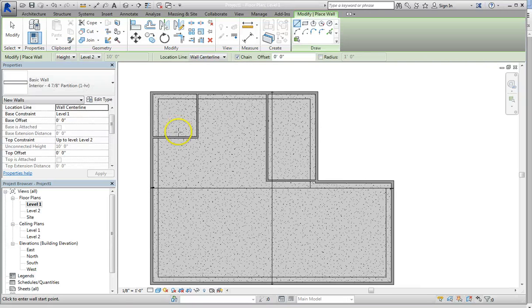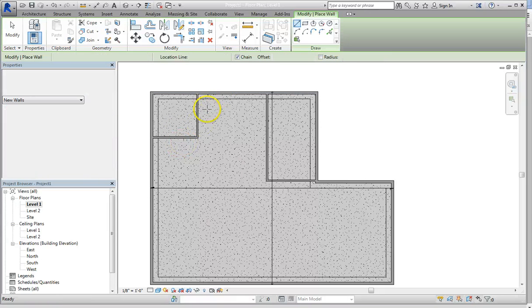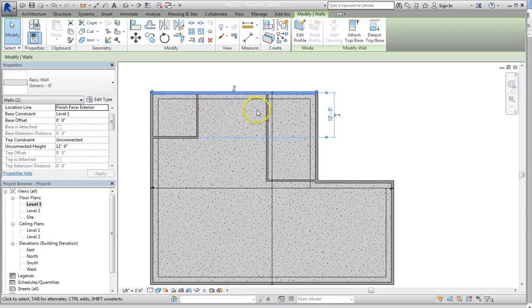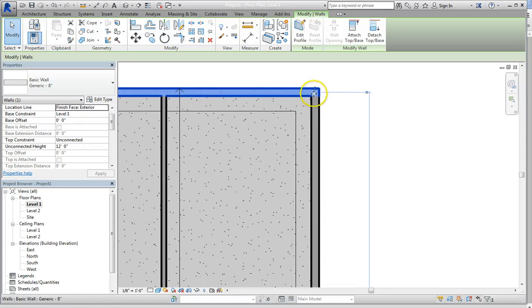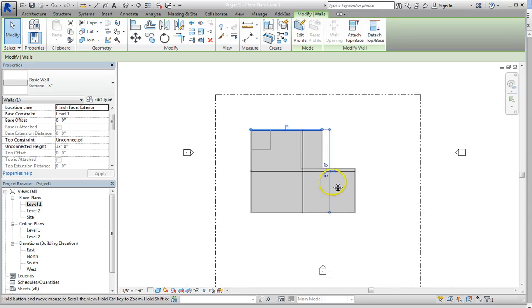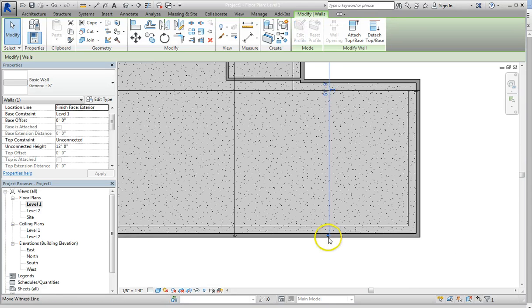After that, last week we talked about dimensions. So we talked about how if you click a wall, dimensions are going to come up. And if we want this dimension to go from exterior to exterior, then we held down our mouse, we dragged it over till it kind of snapped and let go. And then this is still messed up because the dimension's going to the mid of the wall and we want it to go to the exterior. So dimensions on the outside of your house should be going to the exterior.